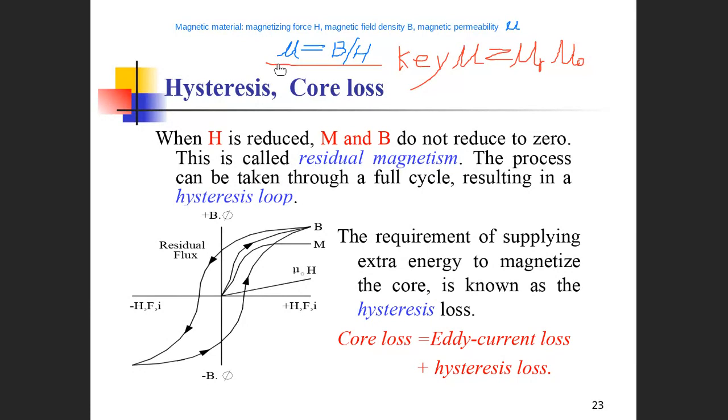So it is the mu that is changing with the current, making the analytic analysis of the magnetic circuit impossible. So at each step we have to confirm the mu. Later on, in the tutorial examples, we will show you how to determine the mu. Anyway, by this chance, we have a thorough revision on the magnetic materials. Particularly, we have emphasized the concept of permeability, which is changing with current.